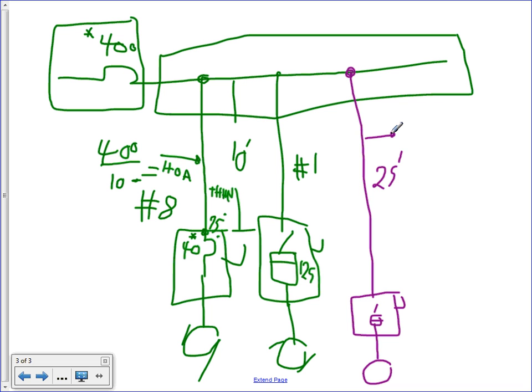The rules are the same. The conductors that you tap have to be terminated at a fuse or a circuit breaker, or a set of fuses or circuit breakers, that limit the current to the maximum current that the conductor can carry under these circumstances. So let's go find the conductor. And you have to put it in a conduit to protect it from physical damage. And rule number 3, the most important: the conductor size cannot be less than 1/3 of the overcurrent device, which is 400.